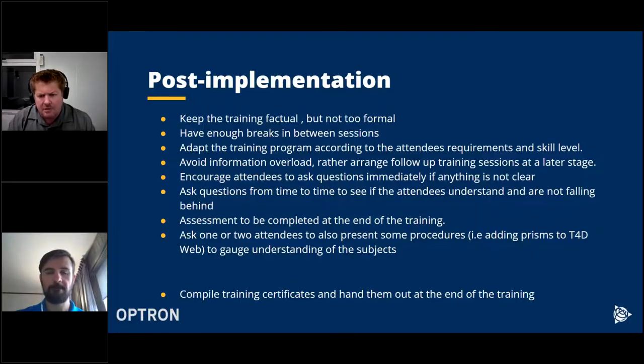And especially if it's a country or a region where they get lots of lightning, we will actually ask the client to install an earth spike at the location so that it can be earthed and protected from the lightning as well.